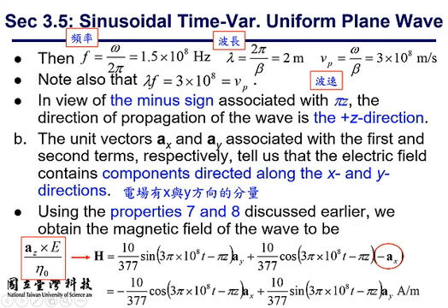So the first vector we put in here is AZ cross E, the electrical field, divided by eta sub 0. Why do we need to divide by eta sub 0? Because the ratio of electrical and magnetic field is eta sub 0 in free space. So you need eta sub 0 to get the correct magnitude for the magnetic field.